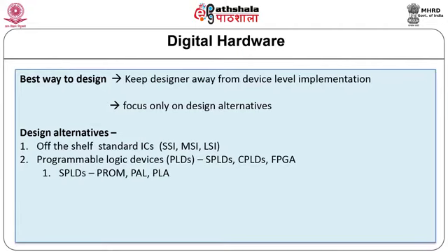In addition, none of the design software utilizes the off-the-shelf ICs, SSIs and MSIs, and thus automation in design is really impossible. As the programmable devices are capable and less expensive, the designers prefer this option over SSI and MSI ICs. There are two types of PLDs: simple programmable logic devices, that is SPLDs, and complex programmable logic devices, CPLDs.